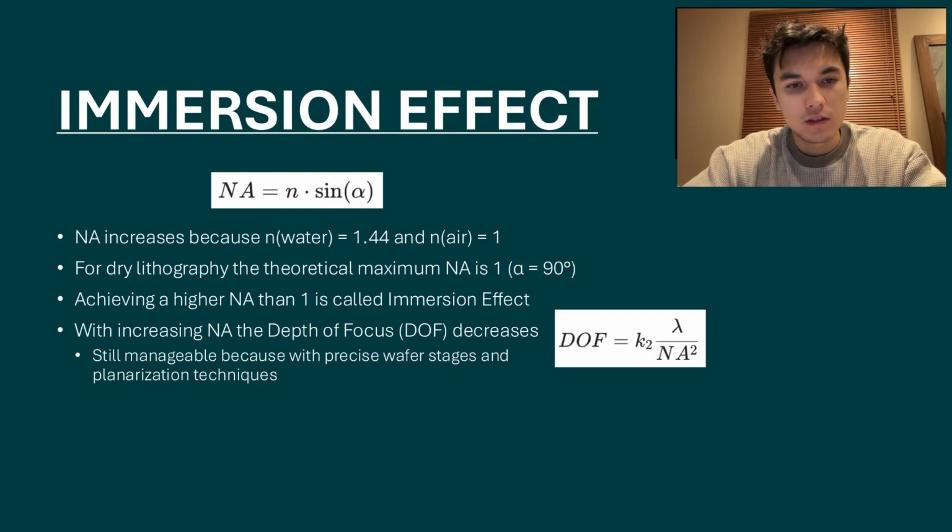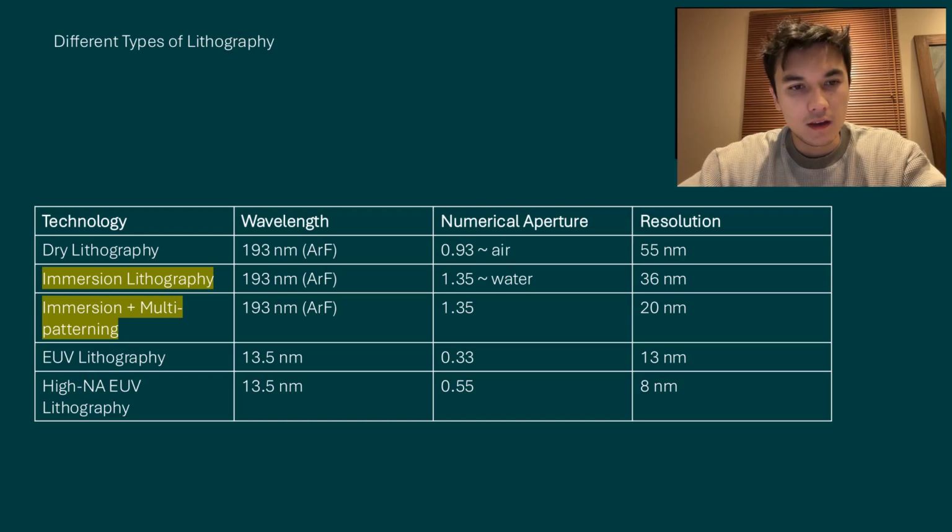But a challenge is that the depth of focus gets decreased with a higher numerical aperture, but it's still manageable because we have precise wafer stages and planarization techniques. On this table, you can see different technologies for lithography.